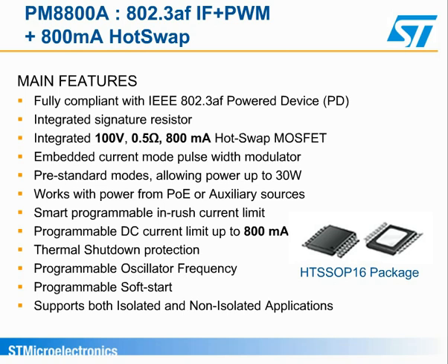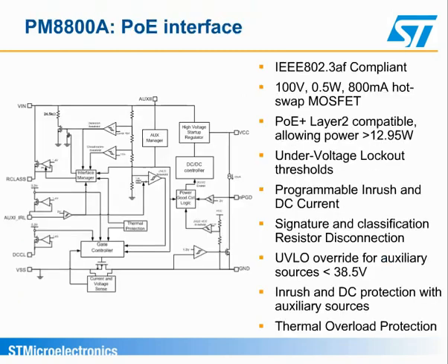The PM8800A is housed in an HTSSOP16 package, which has an exposed pad to give better thermal behavior. Here we can see the internal block diagram of the PM8800A. Depending on the voltage on the input port, different blocks are activated to comply with IEEE 802.3af.